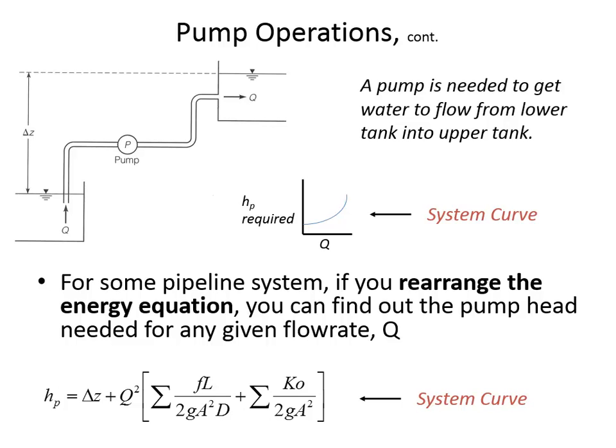If it is flush with the wall, it tells you that would be a 0.5 for an entrance like that. If it's rounded, then the K value is a little bit lower because it causes less turbulence. If the pipe extends into the reservoir like this or like that, then the K value is 1.0. And anytime you have water discharging into a tank, K is 1.